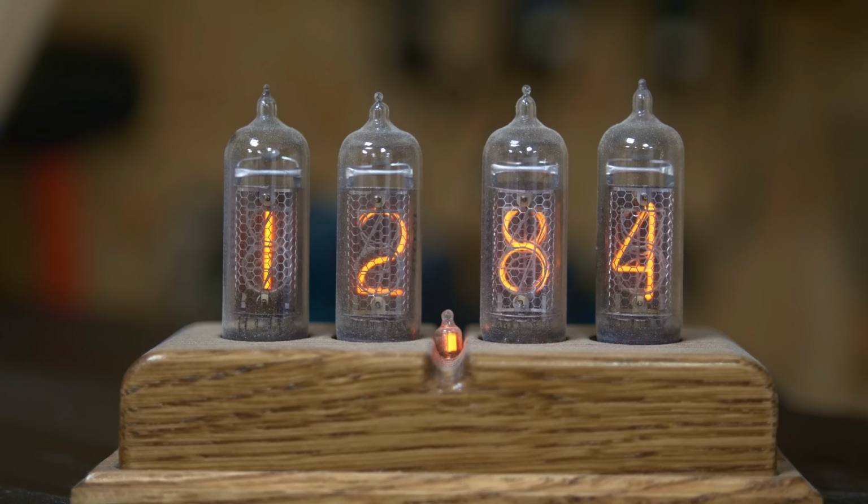To maximize contrast under bright ambient light, ideally the glowing element of the display should be directly viewable, which was one of the Nixie tube's greatest strengths. So you might just make a 7-segment Nixie tube, which was indeed a thing, more or less. But glowing neon cathodes still needed the same high voltage DC as ordinary Nixies, which was annoying and expensive to implement. Luckily, the vacuum fluorescent display had just popped on the scene.